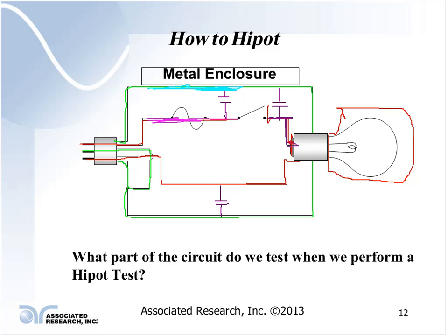So if you test a product and you see that it's drawing 1 milliamp, you test another one and it's drawing about 1.02, and another one 1.05, and another one maybe 0.98, okay? So you're right around the 1 milliamp point. So where do you set your trip? You might want to set it to something slightly higher than that. Let's give it a 50% margin, even. Let's go to 2 milliamps.